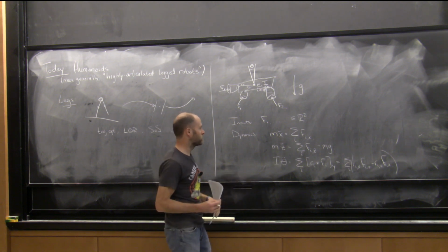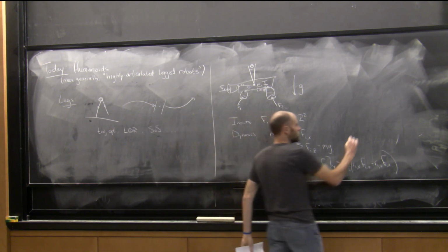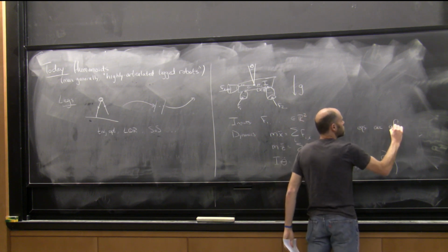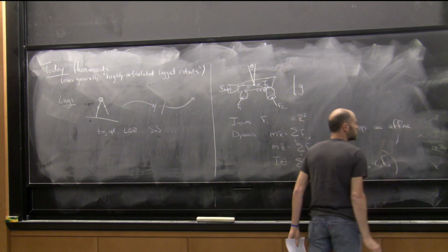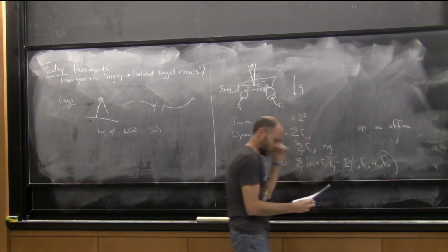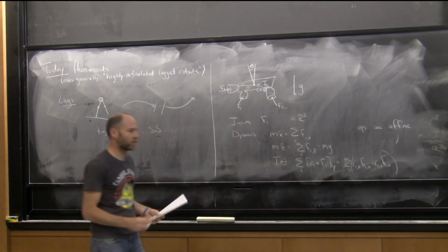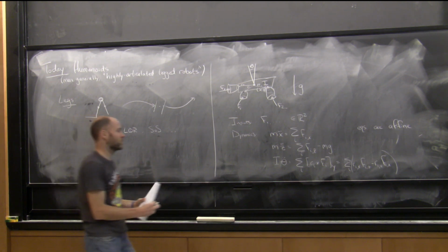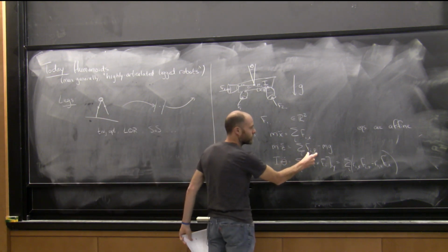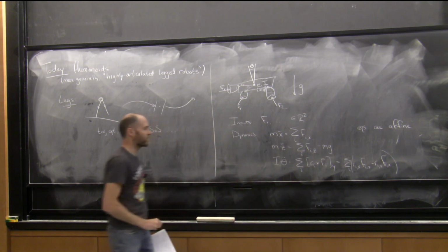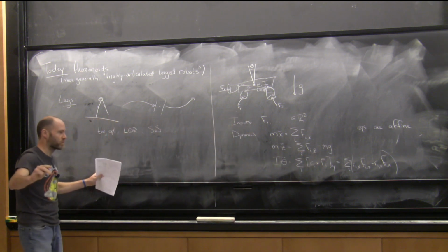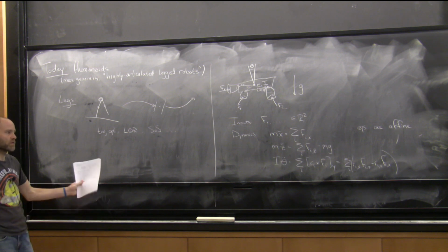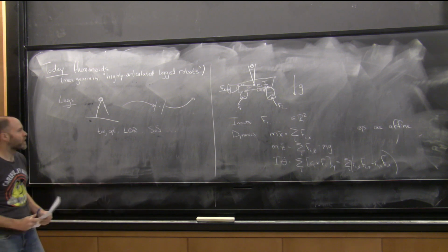This is actually an affine dynamical system. I can use all my standard tricks to control it. I can change coordinates and do LQR if I want to stabilize it. I just have to have some thrust that cancels that out to get rid of the affine term. I can do trajectory optimization with convex optimization. I can do all my tools, right?